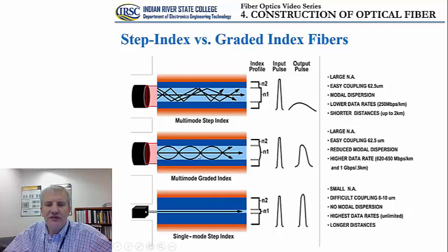That's going to affect the total length that certain modes propagate in the glass core. They will arrive at the other side of the optical fiber much sooner than in the case of the modes in the stepped index fiber. That has an important impact on the total amount of dispersion that occurs in the graded index fiber.